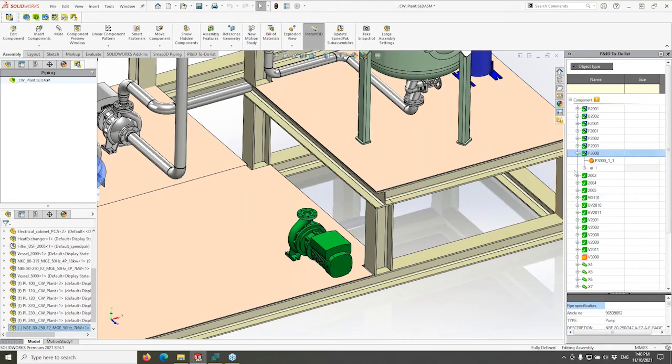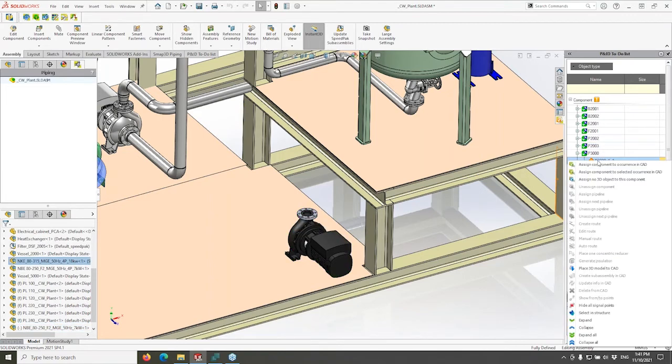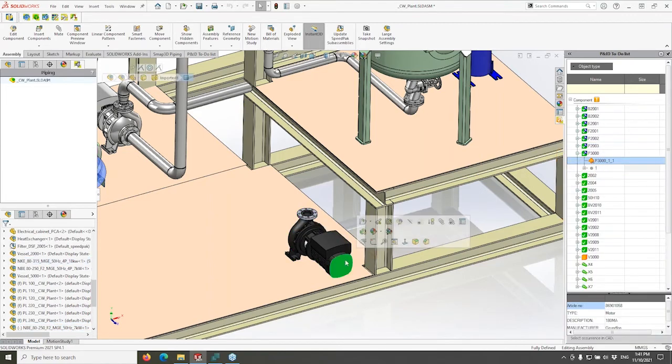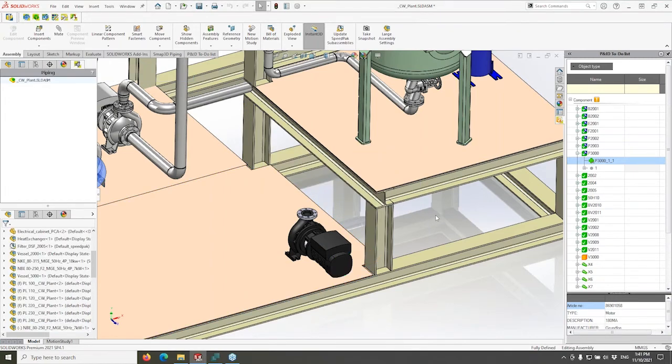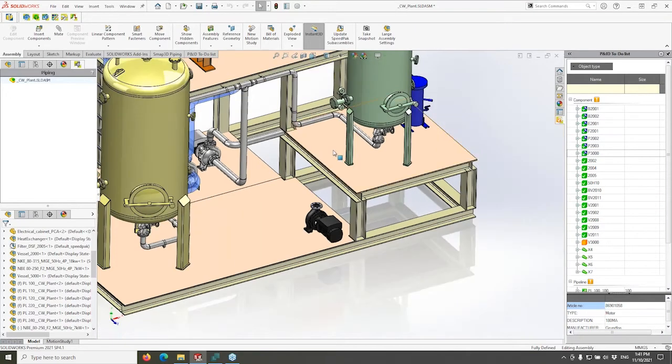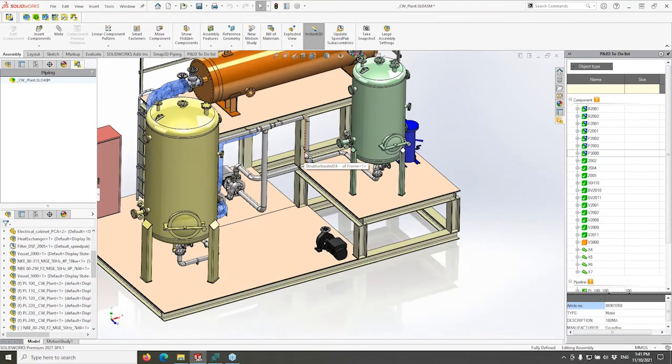Now, do we want to have more granular control over that pump and the separate motor? If so, we can come in here and we can actually assign the components manually. Okay? If they aren't something that you use on a regular basis, you could just download the assembly, put it into your SolidWorks model, and then manually assign things as well. Okay? So it really works both ways, as to what fits better into your workflow of how you get data into your company or for your designs.